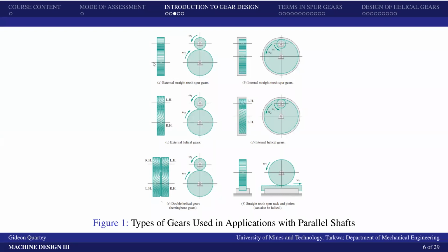Over here you see this is the axis of the gear, and that's the axis of the pinion. The axis of the gear is parallel to that of the pinion, and the gears are meshing somewhere here. So in such cases, the axes of the output shaft and the input shaft are parallel, and you will see this view too, where the axis of the pinion and that of the gear match.